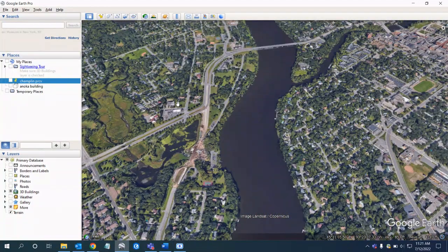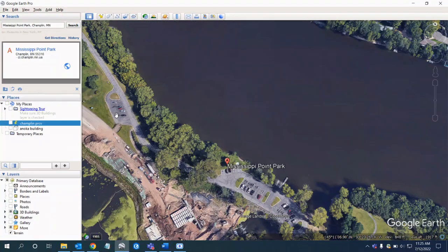To perform a visual analysis, the main tools that you will use are Placemark and Polygon. Before moving on, make sure that the Terrain layer and 3D Building layer are turned on in the Layers tab on the bottom left. For demonstration purposes, I will be simulating a hypothetical building proposed in a park in Anoka. According to the MRCCA rules, this area is in the River Towns and Crossing District, or RTC, where buildings over 48 feet can only be approved with a conditional use permit. This would require a visual analysis of impacts to PRCVs.